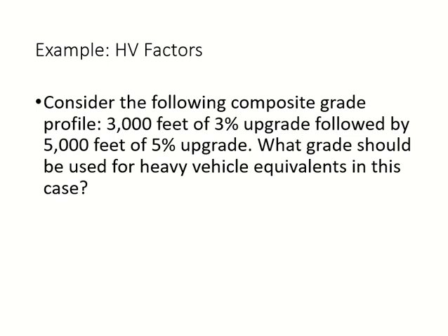Now you can do it for both of them separately. This part of the segment has gradient 1, I will do the entire analysis for this one, and then repeat the whole process with the other gradient. You can do this, but that means you do everything twice. What if I can combine these values into one, so I can do the remaining analysis only once? To combine them, we calculate the average gradient.